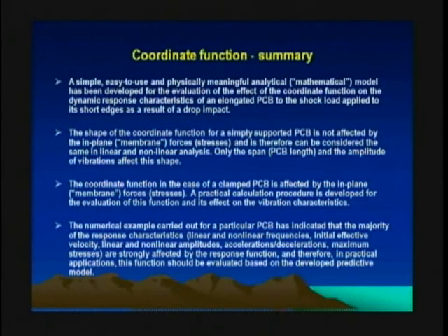So the summary of this analysis is this: a simple, easy to use, and physically meaningful analytical mathematical model has been developed for the evaluation of the effect of the coordinate function on the dynamic response characteristics of an elongated printed circuit board to the shock load applied to its short edges as a result of a drop impact. We considered a situation where I have an elongated printed circuit board which is supported only at the short ends, and not supported at all along the long ends. So in effect it's an elongated beam like a strip. In the first case, we assumed that the short edges were simply supported, and in the second case, they were clamped.